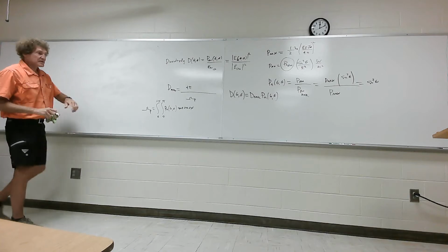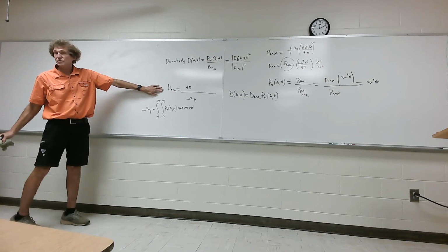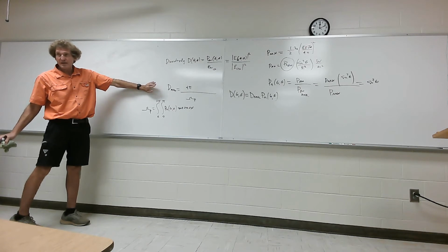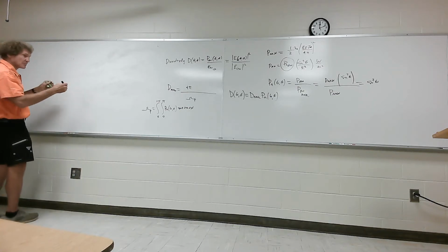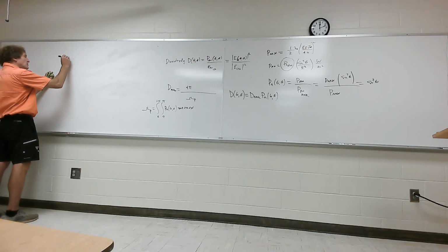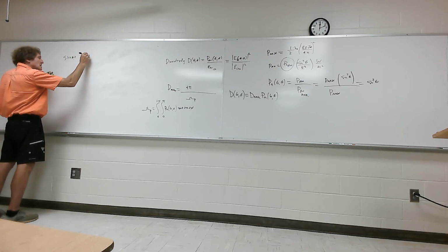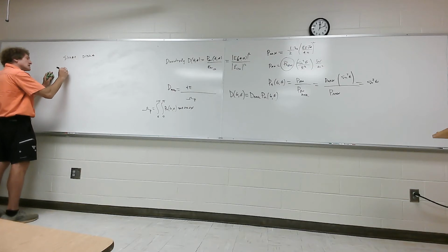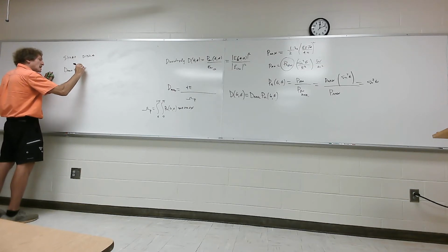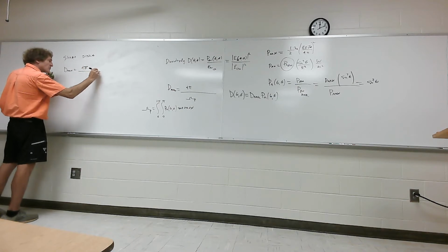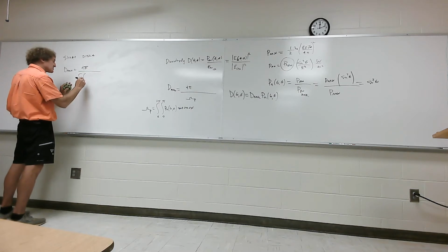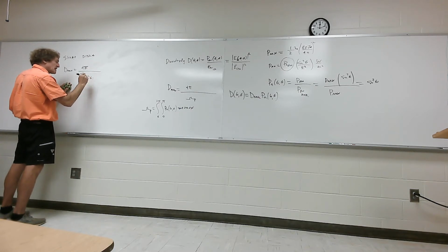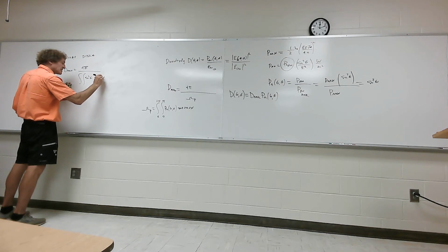So now we do this calculation. Be attentive here. This is one you're going to be required to be able to do. And you can thank God that your calculators do symbolic integration, because it saves you a lot of anguish sometimes. But I'm going to go through it the normal way. So when I calculate D max, this is for a short dipole. The equation says D max is 4 pi over, now I have a double integral of the normalized power density, which is sine squared, right? Times sine of theta, d theta, d phi.